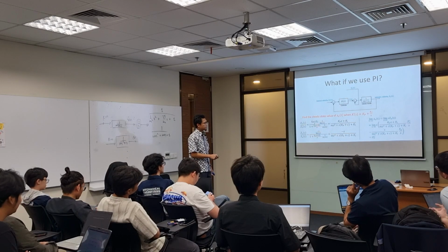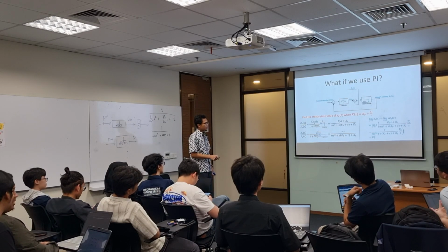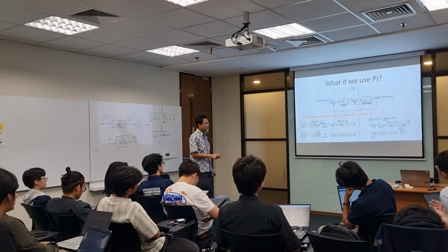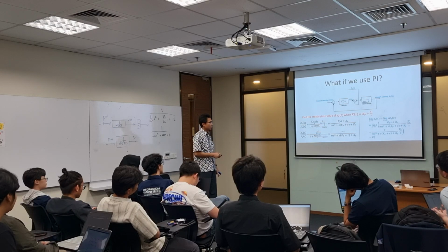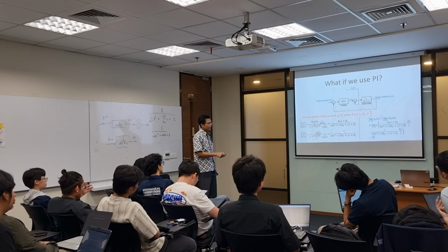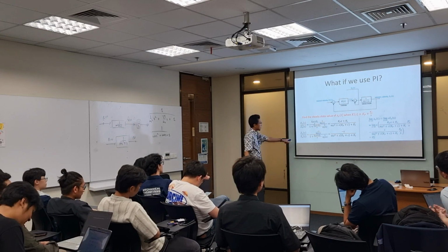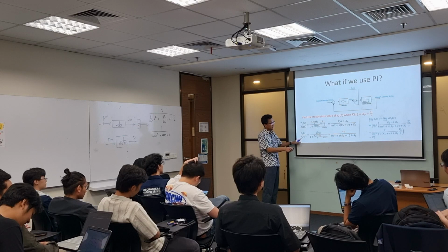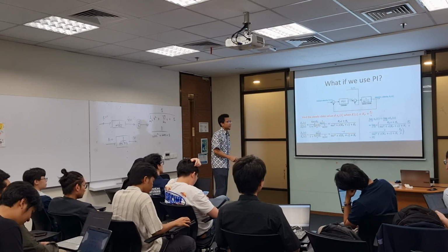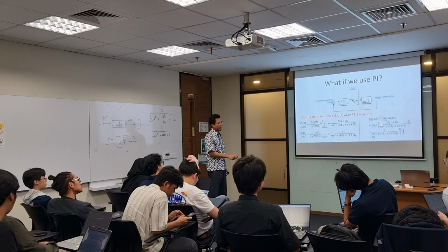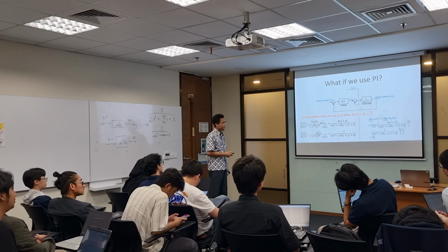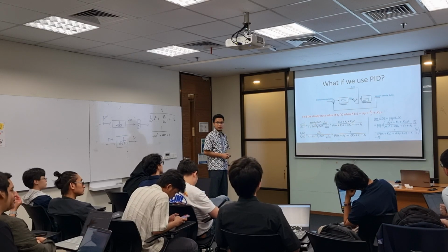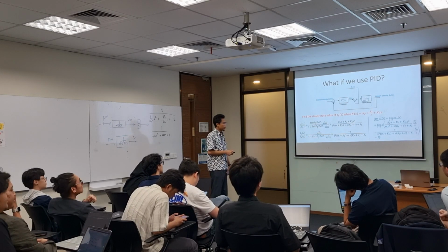So when we have the s on the top here, this s eliminates the disturbance. The Ki term that we have, Ki over s, makes the s come out for the FW. Based on that, the steady state value is equal to the desired velocity. So we eliminate the disturbance. What if we use the PID? This is the case when we use PID.